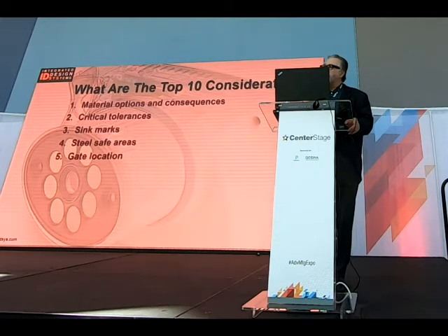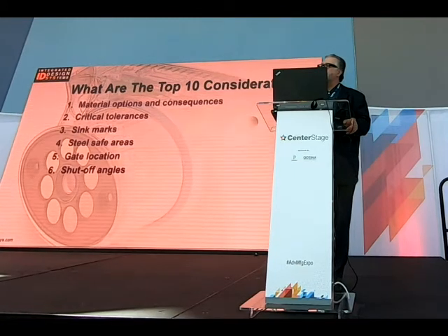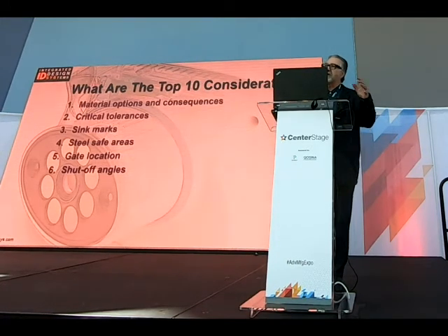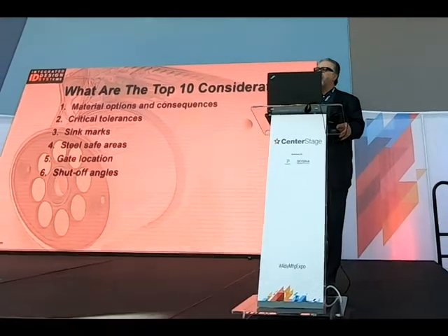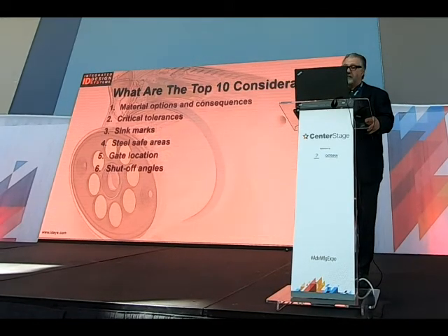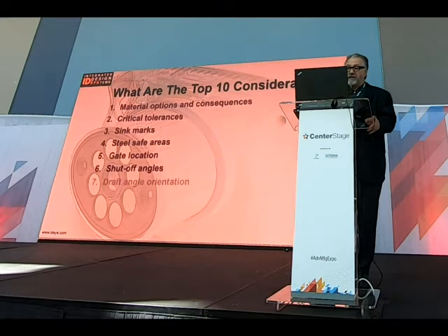Gate location is another major decision that not only affects the structural integrity of the part, but also its appearance and fit. Shutoff angles is a term used to define the geometry of a part where you have steel past the core and cavity of the mold passing each other, and you don't want the features in those areas too steep or with a limited amount of draft, where you end up getting balling of the parts, eventual flash, and a lot of tool maintenance.